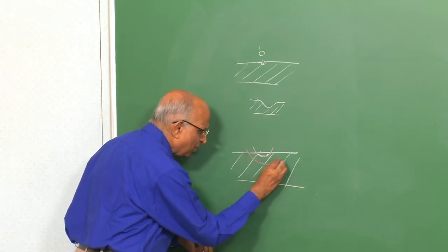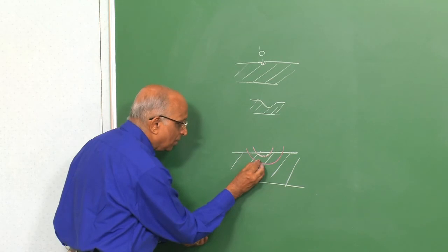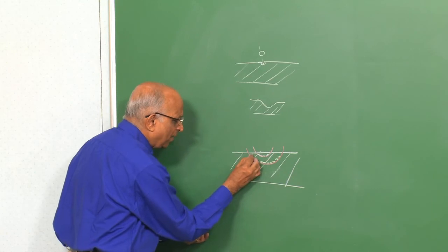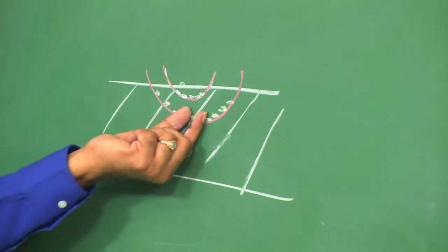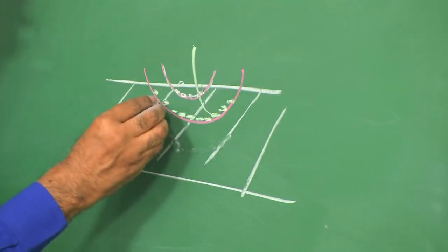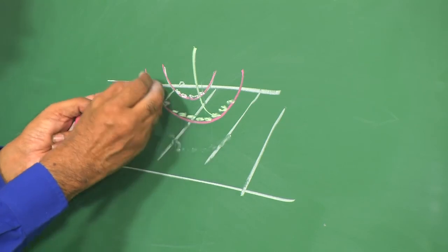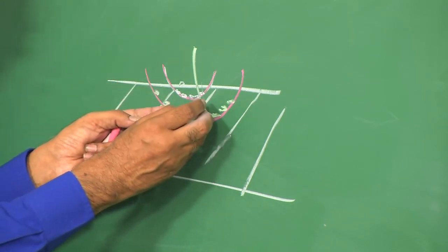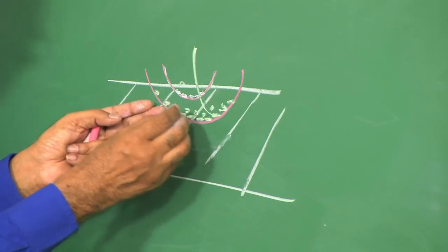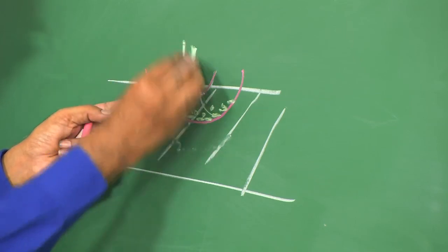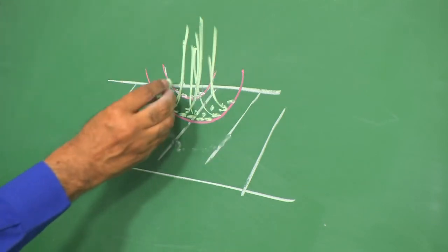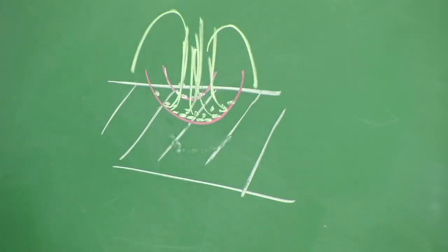I have a spherical blast wave over here, and the earth which is being compressed gets into the plastic state. Behind the blast wave, I have the expansion fan, that means the pressure is reducing. When the earth gets into the plastic state and crumbles, I have fragments of the earth, and because of the pressure decrease, all these things now have a velocity. Because of the low pressure, they are all thrown up, and these things fall back over here, and therefore what am I going to get?